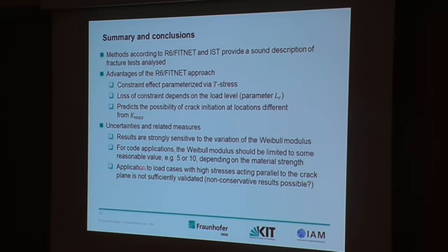And also, there are still some uncertainties in the application of these methods for the cases where we have a high stress component parallel to the crack front. This is the issue of out-of-plane constraint, and I think in such cases this method should maybe not be applied without validation.